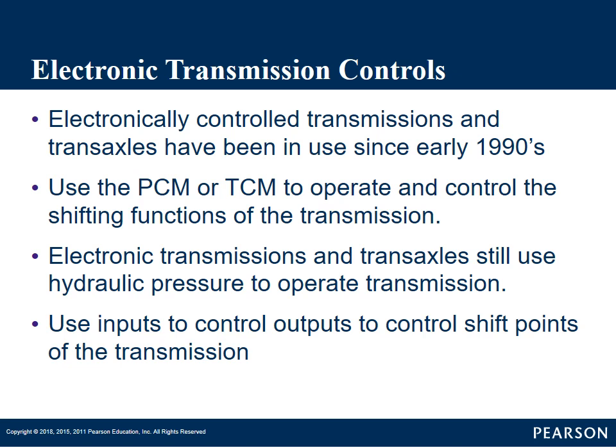That's also another reason, as we replace transmissions, a lot of your newer transmissions need to have that module reprogrammed or reflashed. Even separate transmission control modules, you're seeing more and more of those that need to be reflashed before we drive that new transmission.